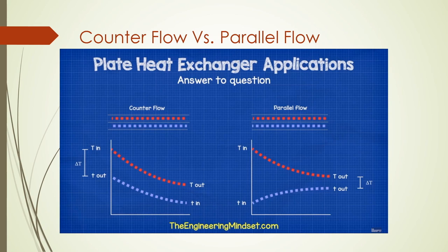Whereas in counterflow, fluids flow in opposite direction. So there is a lower inlet temperature difference. But as the two fluids travel through the heat exchanger in opposite direction, the fluid constantly passes new fluid which has a higher temperature gradient. This constant temperature difference along the entire length of the heat exchanger makes it much harder to reach the same temperature, and so more heat is transferred.